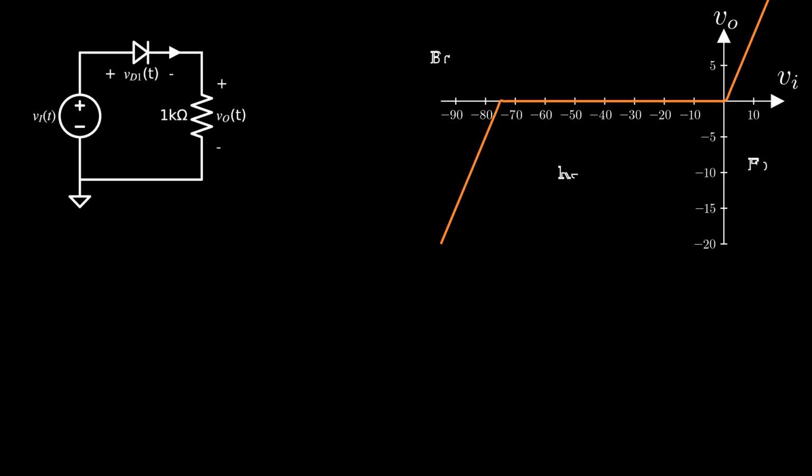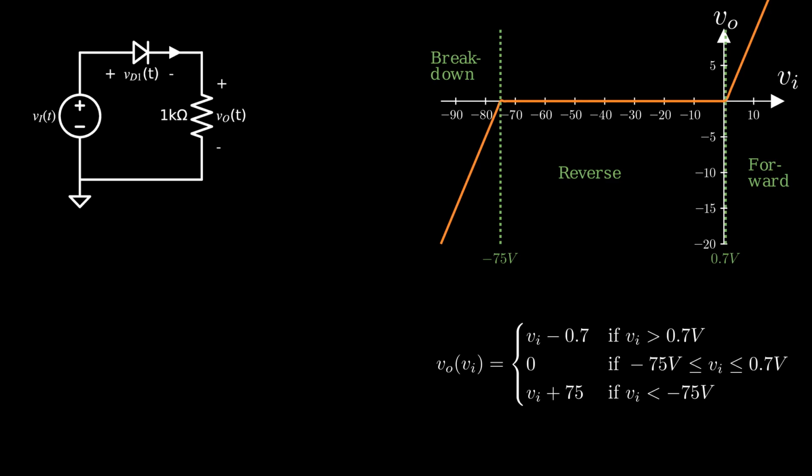We can develop the relationship graphically, or as a piecewise function. We call either of the forms transfer characteristics. This one is a relationship between two voltages, so we call it a voltage transfer characteristic. But you may run into problems where this is not the case, so we'll keep the more general term. This analysis assumes that the signal is of low enough frequency that we can ignore any reactive components.